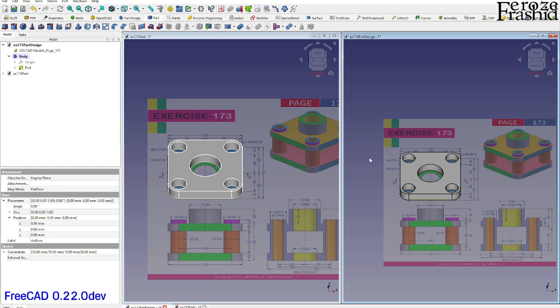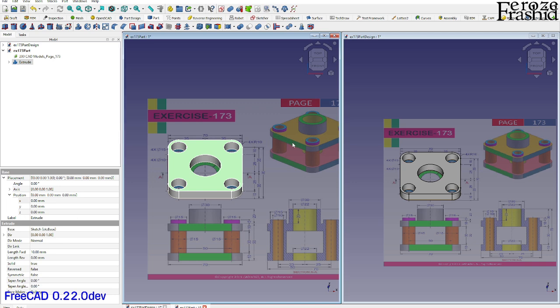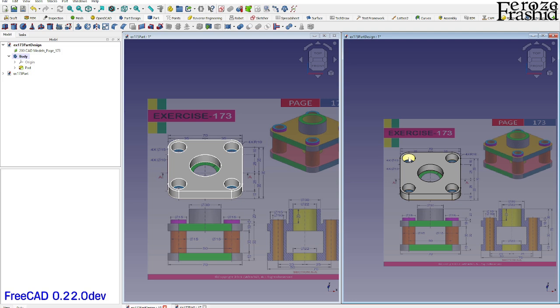Now the next step is, when it comes to Part Design, we have to build these 4 corners or the big cylinder in the middle as the second step. In Part Design, we have a little bit of freedom. We can take this and copy and paste it 40 millimeters above. That's either building these corner holes, but in Part Design it has to be a continuous progression. So let's pick that. We will build 4 cylindrical holes in here.